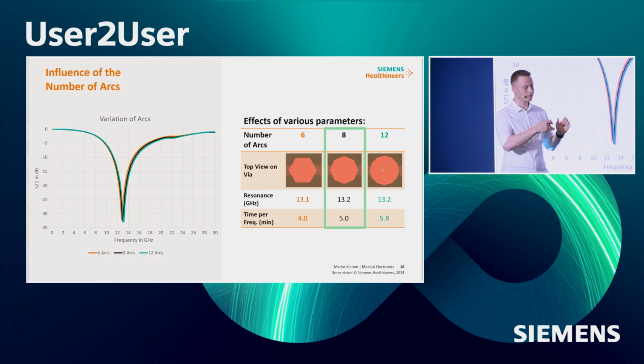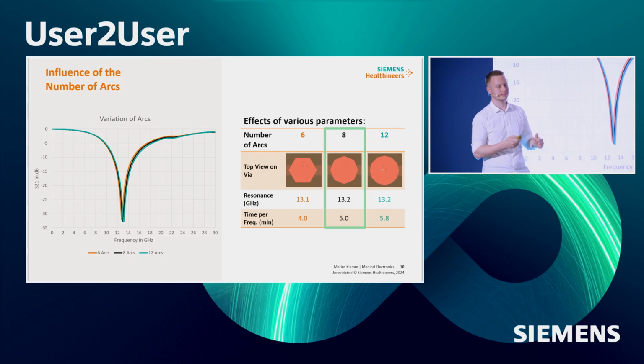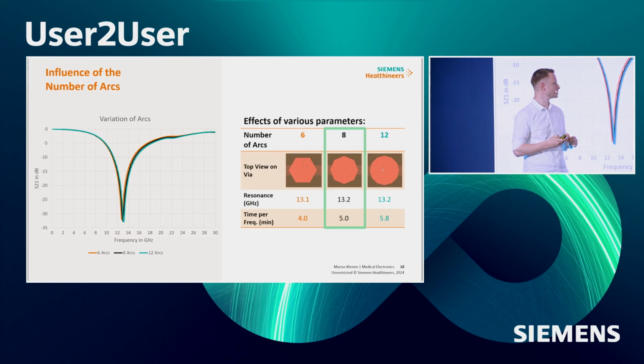The time increase is okay for us if we take 10. If you take 8, the resolution can be a little bit better if you're using multiple stitching vias for ground, or if we're having more complex structures within this area, then 8 would be a good parameter to use.